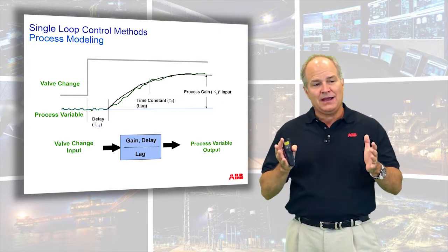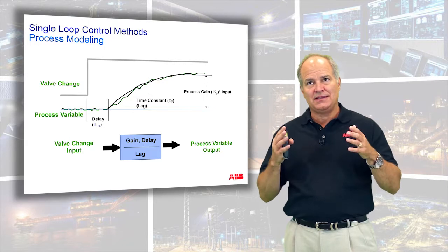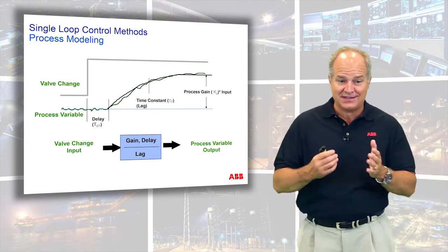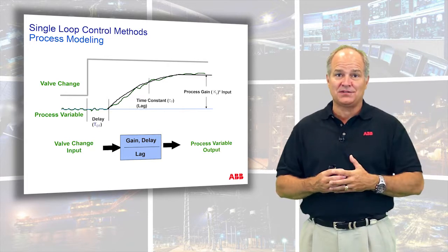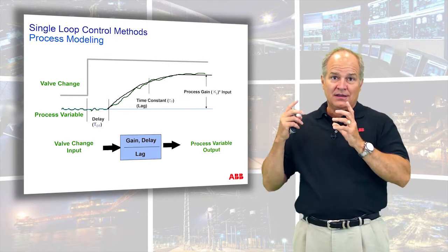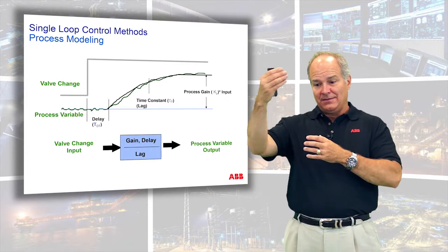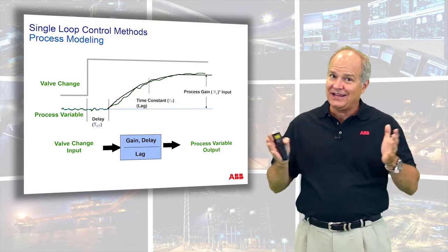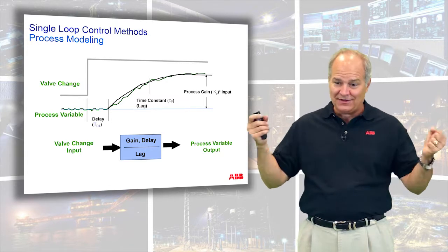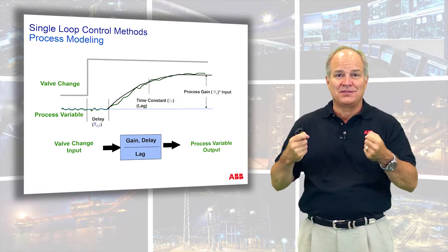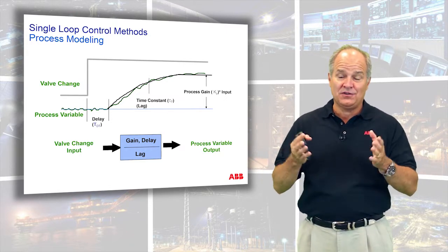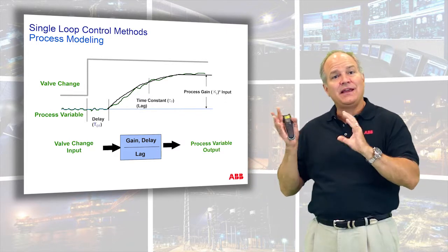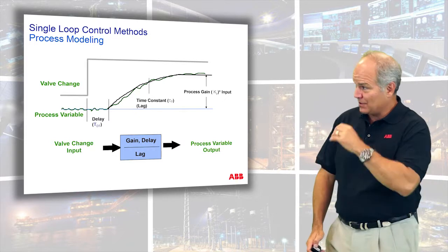One thing I just point out here, a lot of people, when we're doing this, it doesn't actually subtract dead time from the process. It still takes that long to show up at the sensor. But internally, the control is expecting the process very, very fast. It doesn't actually take out dead time. You actually have to move instruments to replace dead time. If you can do it, that helps immensely. But this is just software, we're faking out the controller. And that's what we're going to show here.